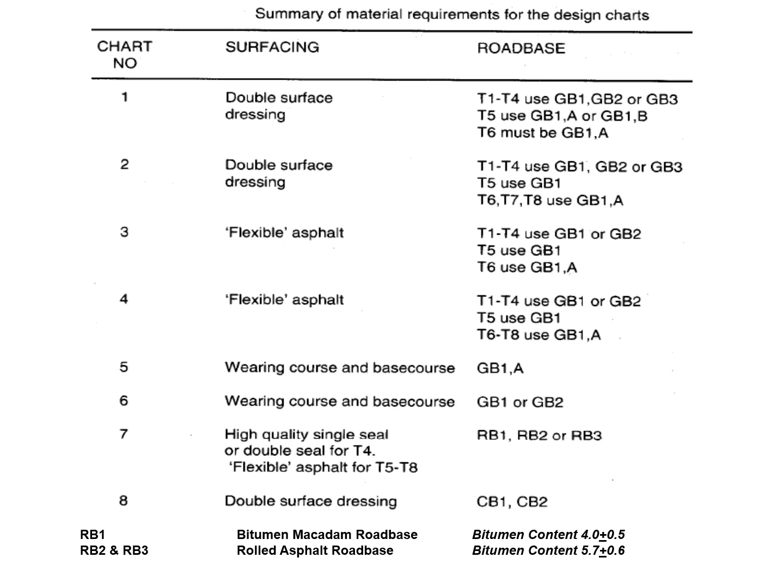Now this particular slide is very important. Summary of material requirements for design charts. In fact, we are going to use 8 different charts in this Road Note 31. You can see for chart number 1 and 2, we are having the double surface dressing. Chart 3 and 4 will be used when we are having the flexible asphalt.